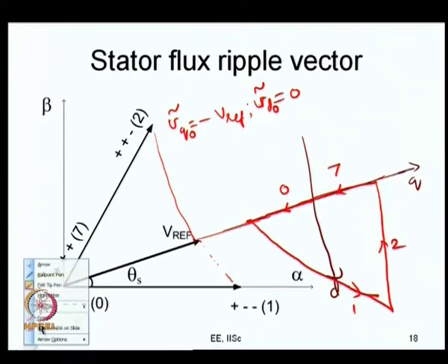Let me just tell you again. So, this is the origin of the dq. So, the time is 0. This is the starting instant of the subcycle duration. For the first tz by 2 seconds in the subcycle, you are applying the 0 state minus minus minus. When you are applying the 0 state, you are applying the null vector, and the desired vector is Vref vector. So, what is the difference? V null vector minus Vref vector, which is actually minus Vref vector.